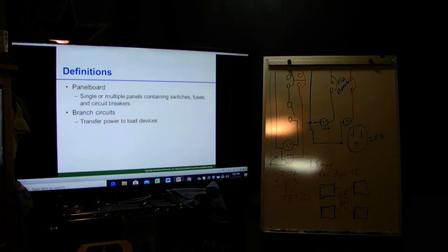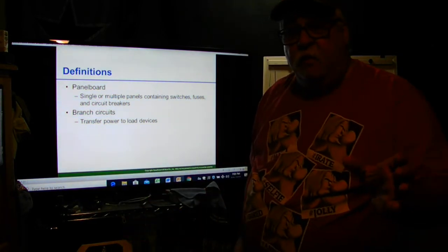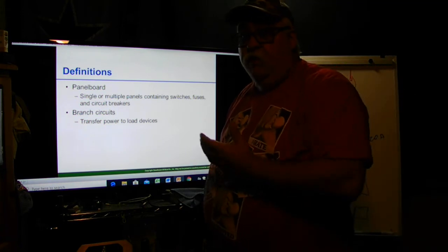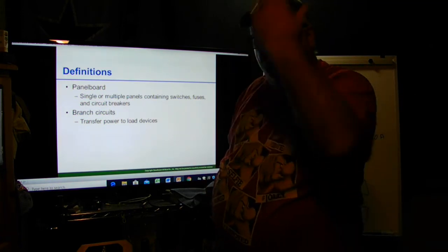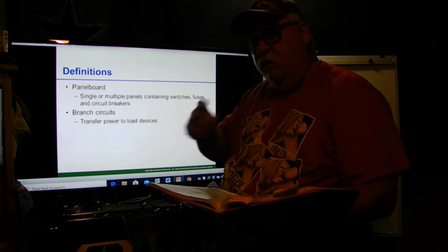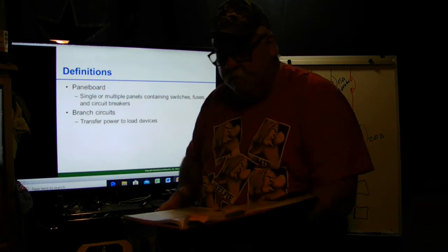They do that a lot, and they may have a 100 amp. Let's say on the first floor they got a 100 amp panel, and on the second floor they have a 100 amp panel, and they feed it with 200 amp wire. So you got 100 amps per panel. So instead of running two conduits, you run one conduit and feed them both, and it's perfectly fine.